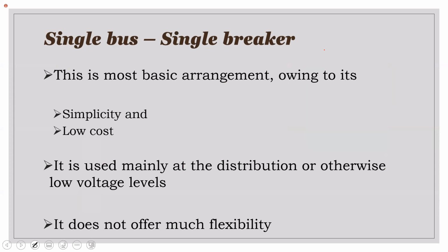Okay? All right. So the first one I want to talk about is a single breaker, single bus. So one bus bar, and to each circuit, you have a single breaker. Right? Very basic arrangement. It works. It is cheap, and it is simple.